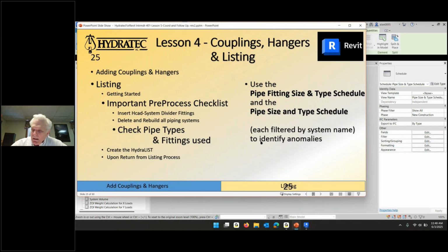And that last one's the one you had done on the riser, I take it? I do believe, yes. I picked the groovelet, and then I picked that divider fitting, and the pipe between them disappeared, and the divider fitting moved down to the groovelet. Yep, nice and easy. Thank you.